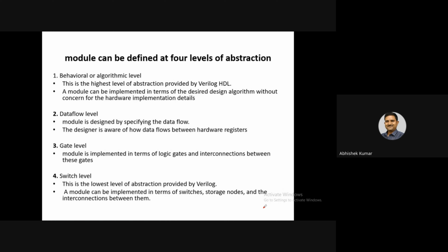Multiplication is implemented via repetitive addition. So in data flow modeling, we specify the operators, but we do not know whether hardware is available for every operator. If the hardware is not available in the IEEE library, it will generate a black box in the output, and this black box cannot be converted into actual hardware logic gates.